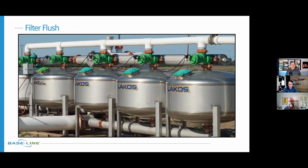Let's look at flushing filters. Irrigation filters need periodic flushing to clear out the debris that's going to collect in there, especially if we're coming from a well. It's going to have more sand and grit. Manual flushes and timed flushes are options, but they're not based on actual needs because it's purely a timer.